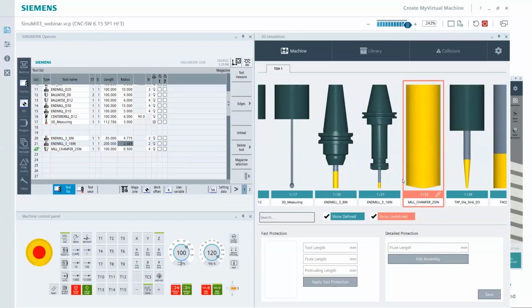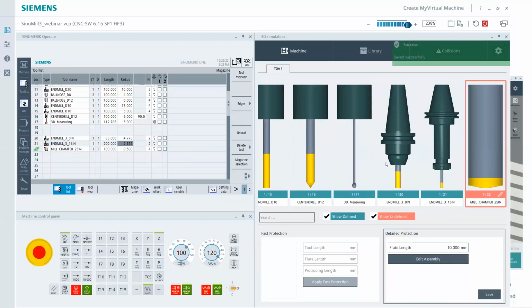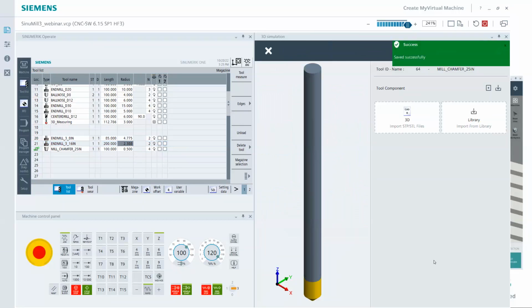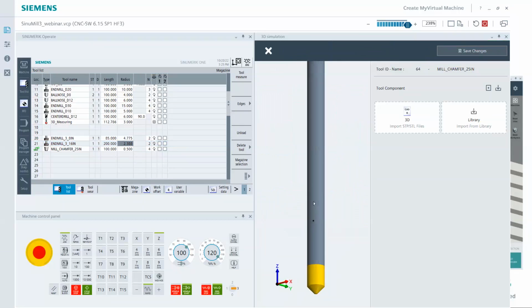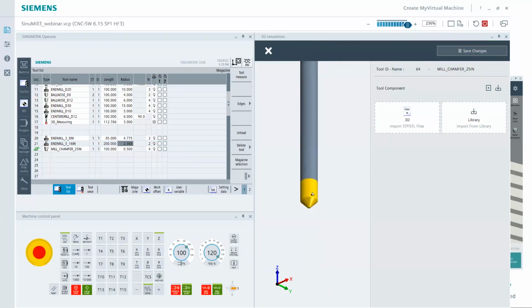Get into our chamfer mill. Now the chamfer looks funny in this little graphical window, but as we come in, and we'll make this small, maybe 10 mil, you'll see I get a much better representation when I actually come into this window right here. So there's your 45 or your included 90. There's our little flat and our true outside diameter.